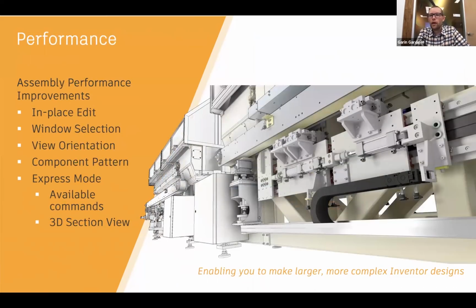And on the performance side, we hear a lot of requests every release around performance. So there was a lot of work done for in-place editing, window selection, view orientation, and component patterns. On the component patterns, if at a part level you have a large pattern that you're making adjustments to, and you're doing that at an assembly level, you kind of get hit twice with making the change. And then if you have an associative pattern for fasteners on there, it has to calculate that too. So now it's generating that pattern much faster, whether it's part or assembly, and you'll see that much quicker in your assemblies.